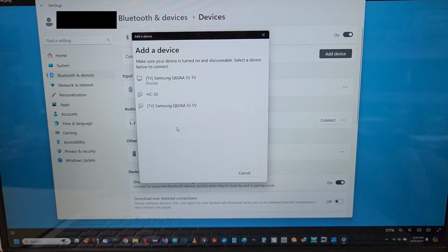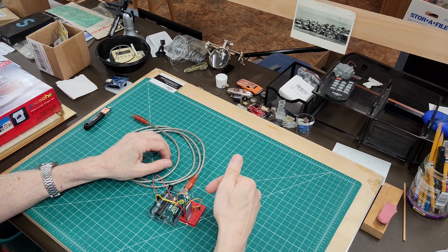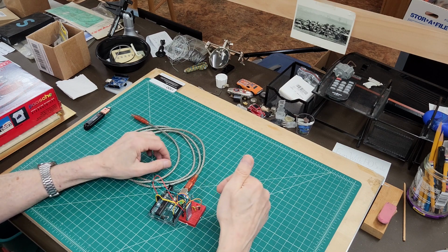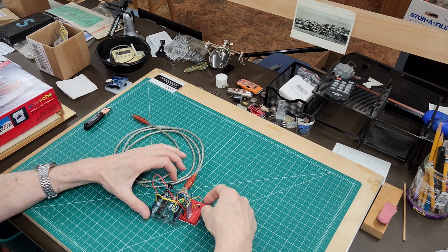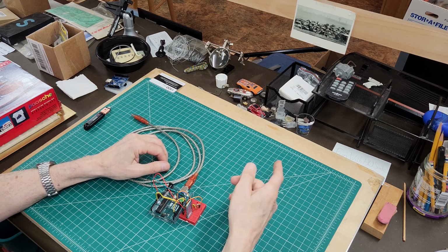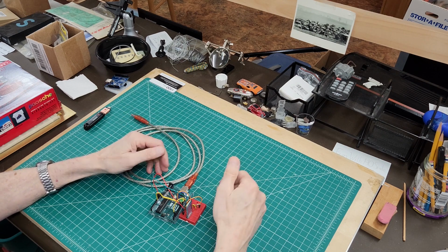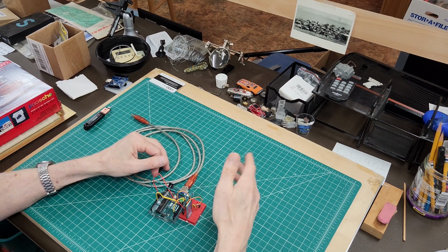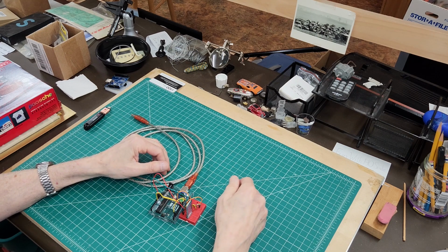The other thing is the matter of the two COM ports created. Once Windows has the Bluetooth connection with the HC05, it's necessary to choose the right one, and you have to choose wisely. I discovered that each time JMRI starts, and there is a configuration it finds for its communication with the DCC controller, JMRI immediately tries to communicate with that controller.